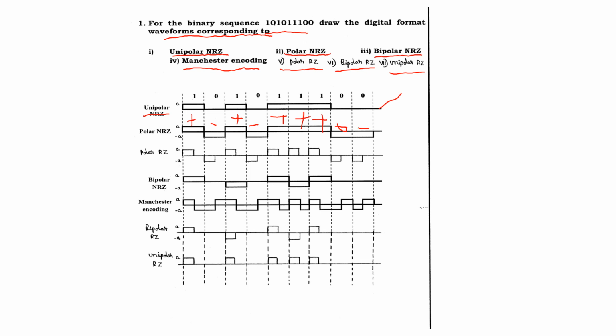So when you transmit that for half of the duration, it becomes polar return to 0. So next is the bipolar non-return to 0 coding. Odd number of ones positive amplitude, even number of ones negative, and 0 is represented with the DC level. So 0 is represented with the DC level, plus, minus, plus, with respect to the DC level.